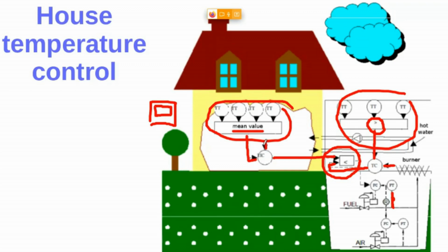Here we have the set point, right, in here. So this is the process variable, this is the manipulated variable, and we select the smallest value, right? This value, this is a controller action, is applied as the input for this flow controller. So we can say that we have a cascade control structure in here.